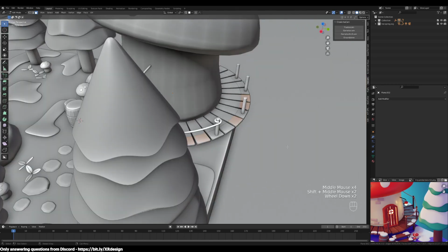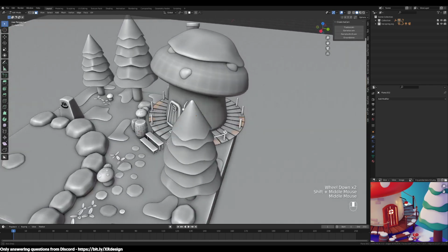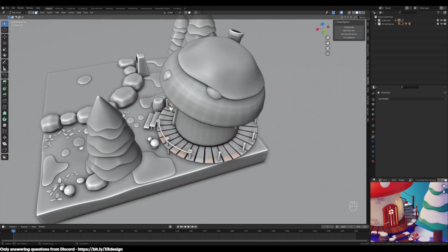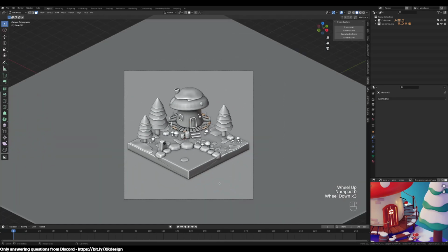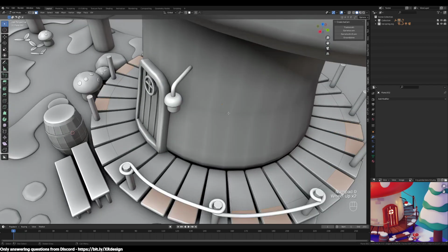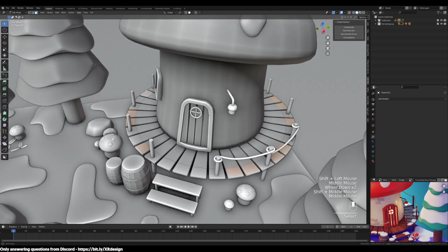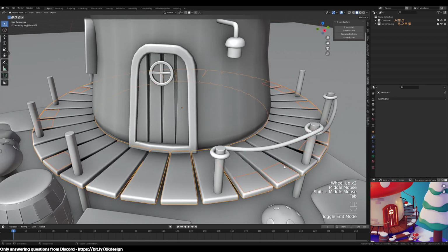In the future, if you say you want to do renders from all four sides of this, then maybe you want to do that. But for myself, I've just been rendering out this view, the front view. So I won't bother doing the back. And once you've done that, let's duplicate it and separate it out. Shift D to duplicate, P to separate.